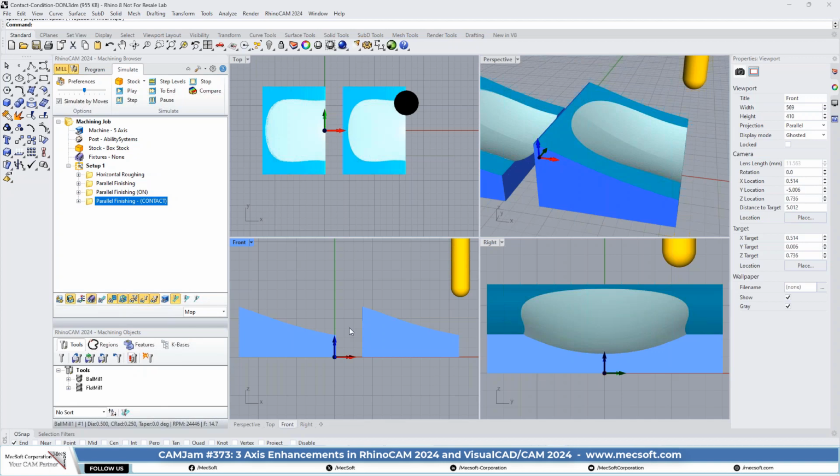So that's why if you see pictures of molded parts, this happens a lot in prototype parts where you're not really trying to be exact, just for the prototype. You'll see a lot of flashing, you'll see mismatching of the parting line, and all that's because the tool had its way with the parting line when it cut. And that's a big no-no in cutting cavities for mold making.